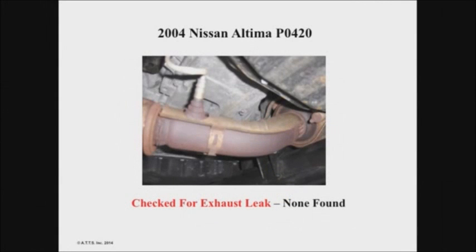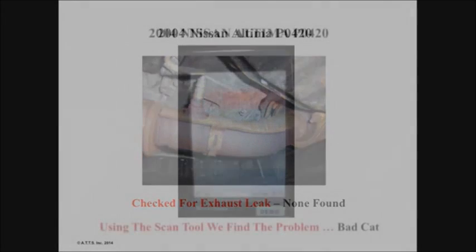They ain't putting shielding on for the hell of it, right? Sometimes it keeps a pipe hot, it keeps a cat warm, whatever the case may be. Sometimes there's nice cracks or exhaust leaks right up top. It's a good way to use a smoke machine and see if you have anything coming out, right? Well, there were no exhaust leaks on this car. It was hunky-dory. Something simple.